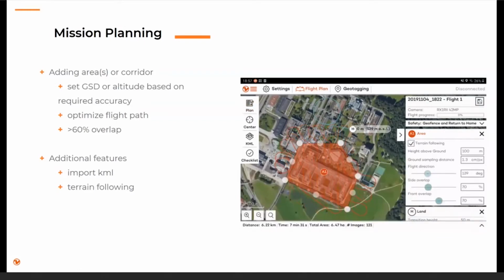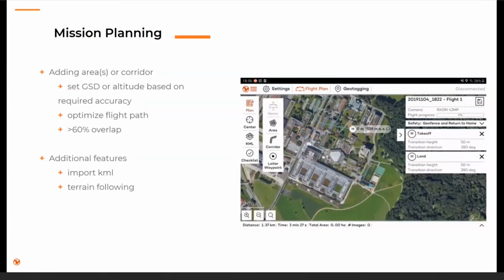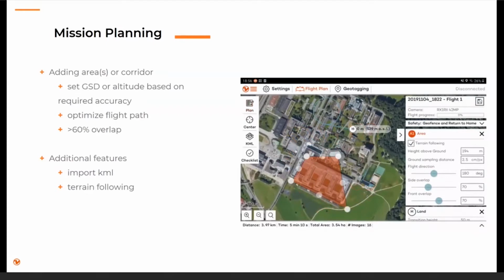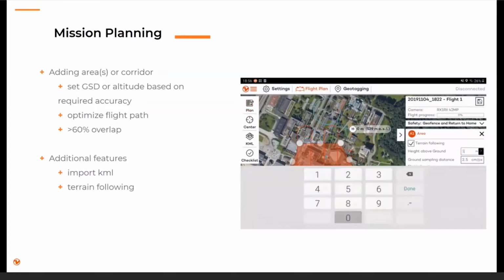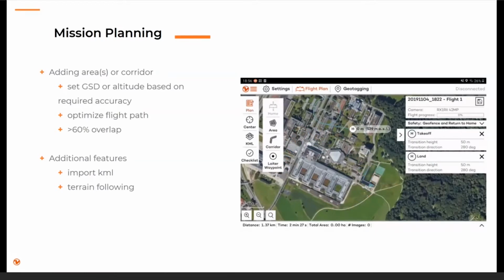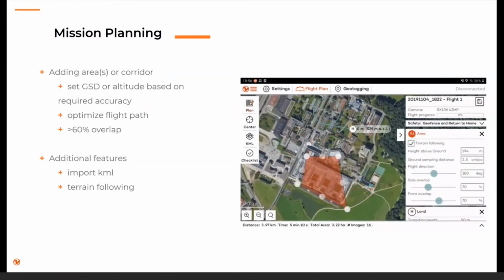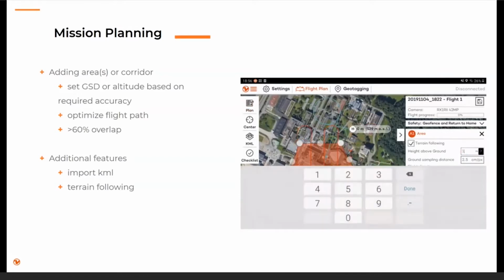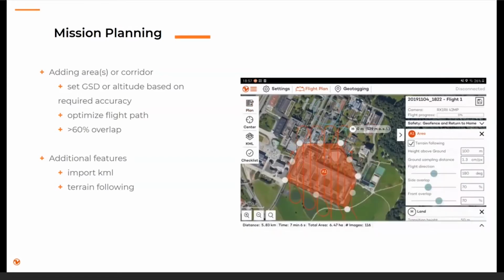Furthermore, the side overlap and front overlap is also very important. Here with the RX1 camera, the high resolution camera, we achieved very good maps down to 60% side and front overlap. But if you map complicated structures, 3D structures, or you have a homogeneous area with, for example, forest that is also moving, we recommend to use more side overlap.